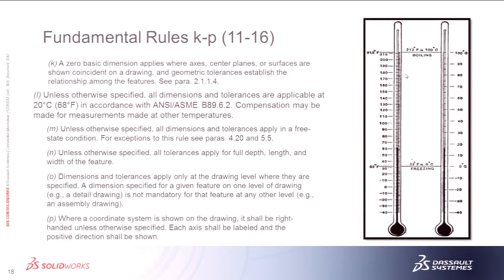Next one's an easy one. Unless otherwise specified, all dimensions and tolerances are applicable at 20 degrees Celsius. So it's in the standard that it should be at 20 degrees Celsius. Anybody who comes from a manufacturing background that has a quality control department, CMM, it's going to be set up in a temperature controlled room, or it should be. If it's not, it should be, because they should be taking those measurements at 20 degrees C. So I hope your quality guy likes it being a little cool.